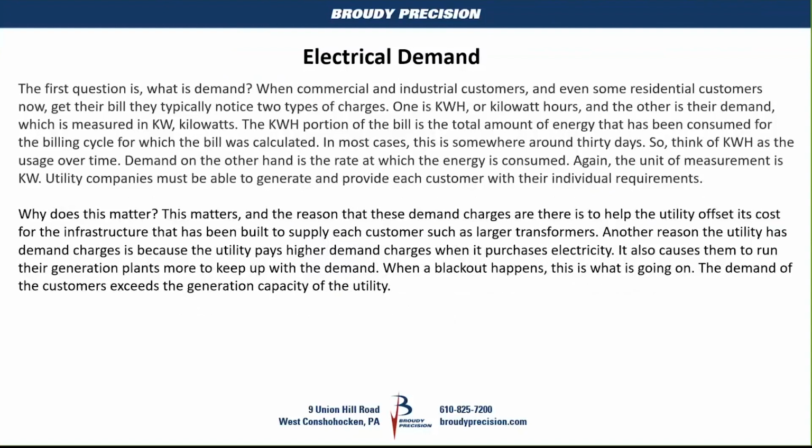So commercial and industrial customers, and even some residential now, get two types of charges. As I said, we get our kilowatt hours, and the other is our demand charge, and that's measured in kilowatts. That's instantaneous, okay? The kilowatt hour portion of the bill is the total amount of energy that is consumed for the billing cycle, and in most cases, it's around 30 days.